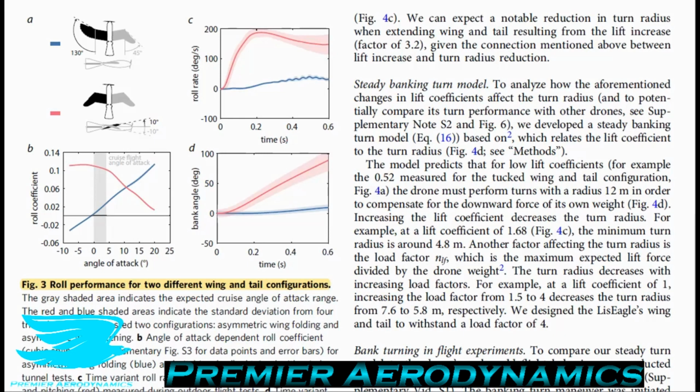The only external variable affecting the roll motion is the aerodynamic roll moment induced by the modifications of the aerodynamic surfaces. So in other words, the only way to actually roll is to change your surface orientations and sizes to initiate this. To decrease the time to reach the desired bank angle, which is beneficial, we want that, and thus improve the roll performance, it is necessary to produce a large rolling moment.